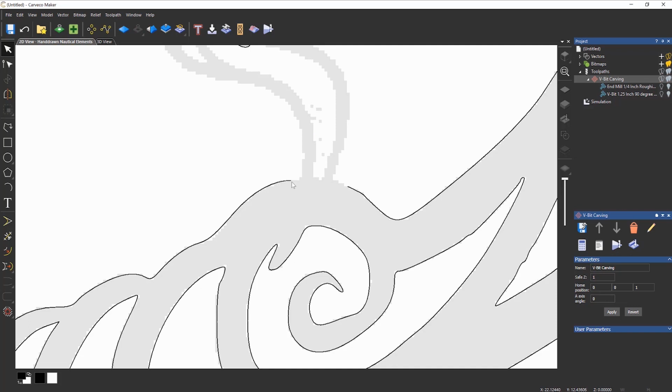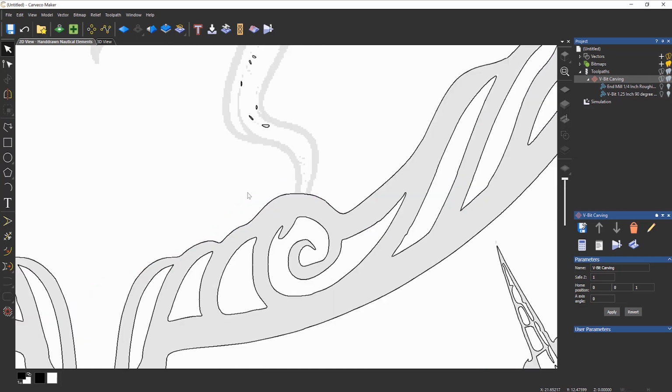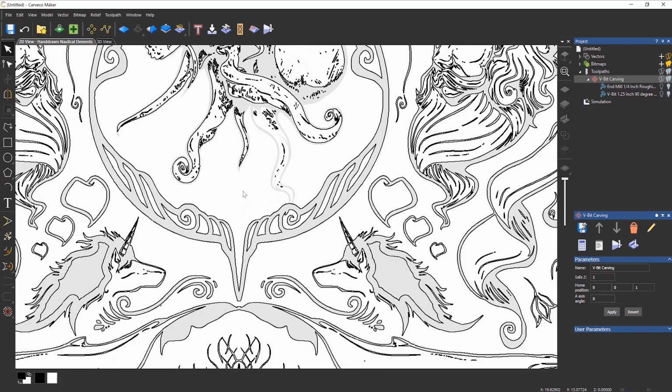Now what I need to do is join this vector up. So if I select there, I'm going to come down to the bottom, and then rather than close with a line, I want to close with a curve. So if I hold the left mouse button down, come over to close vector with a curve. And then I can zoom out.